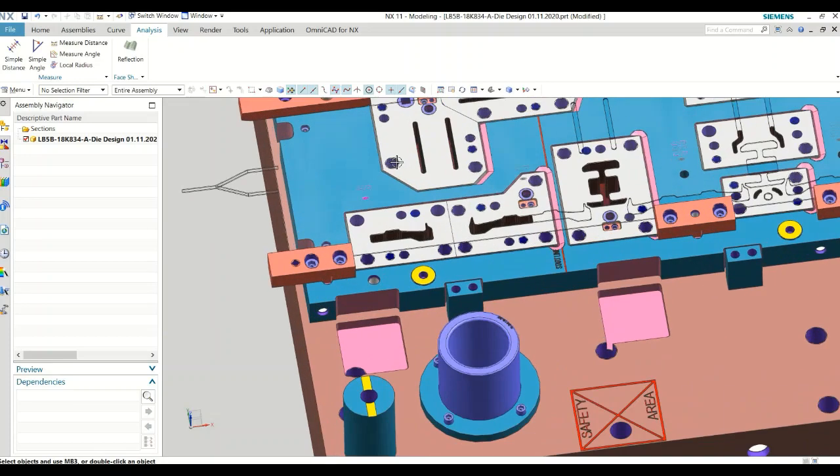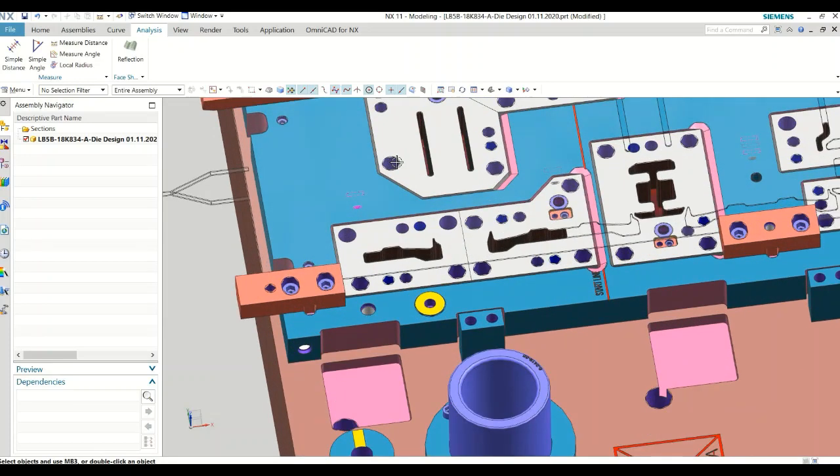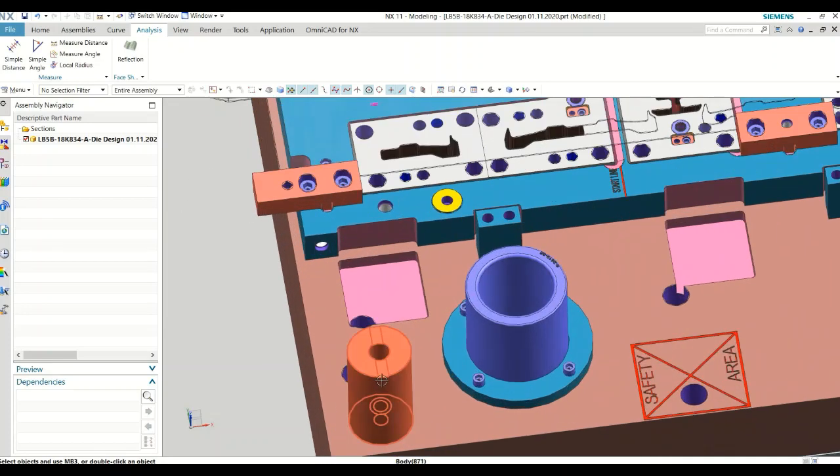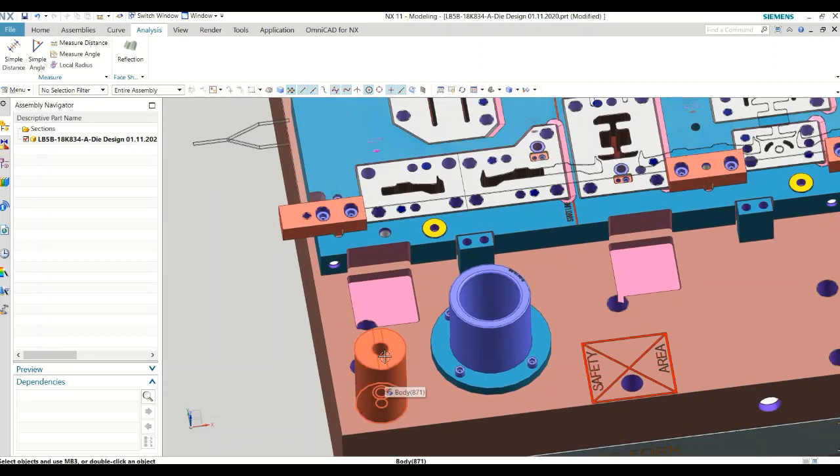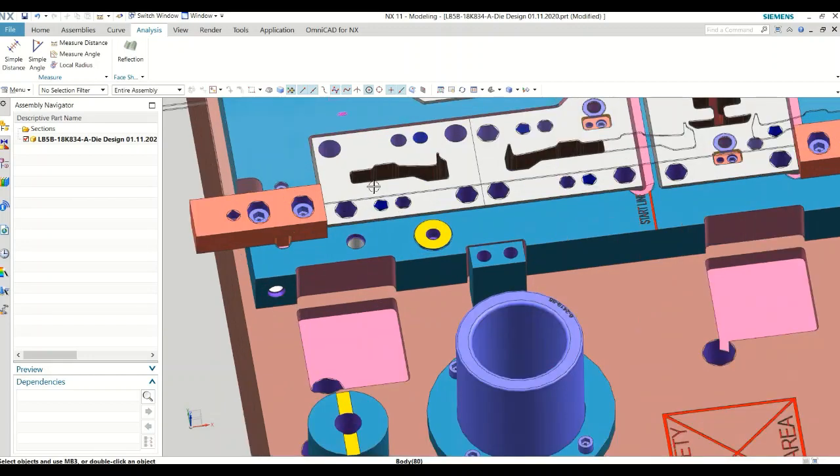Even though the groove is 1.27 mm deep, we sometimes keep it at 1.3 or a little more, so that it does not hit, it just kisses. When it hits, it means you are going to add more pressure, more tonnage. Just kiss it, no more pressure.